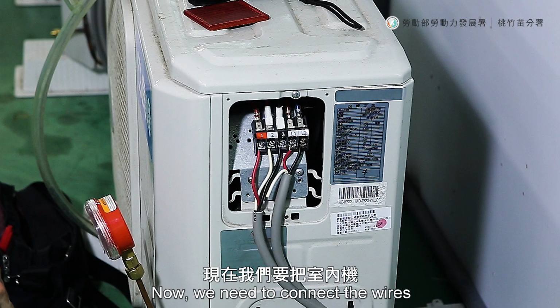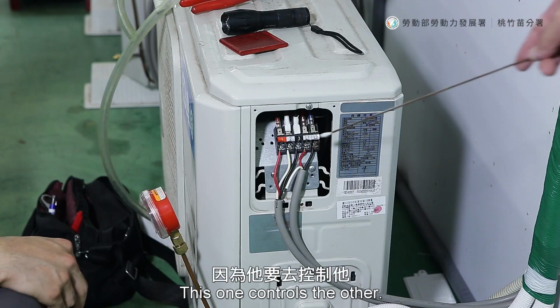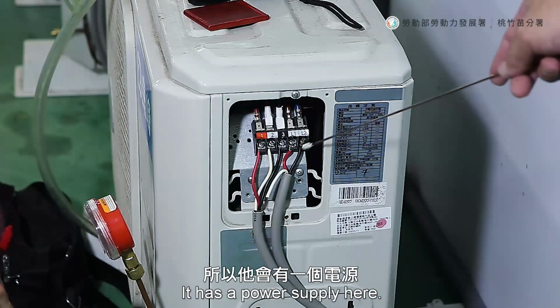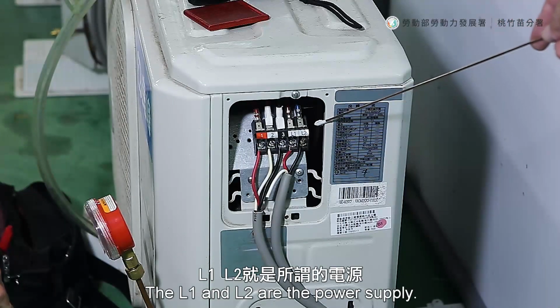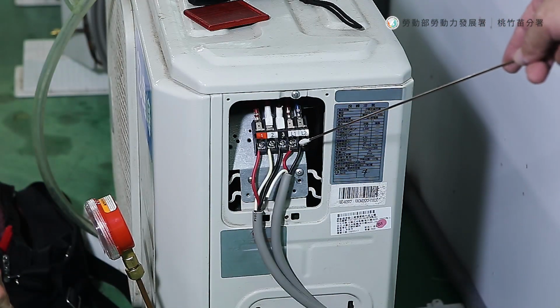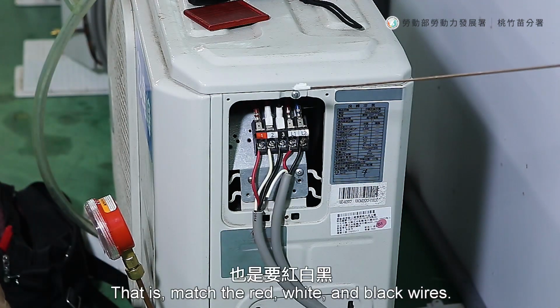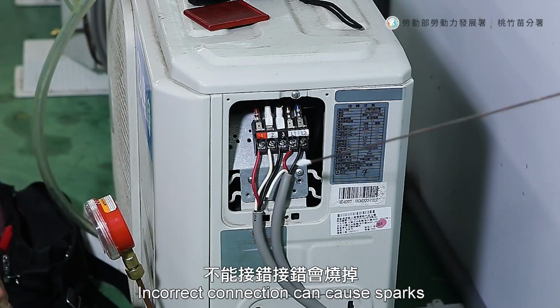Now we need to connect the wires between the indoor and outdoor units. This one controls the other, and this is the power supply from the outdoor unit. It has a power supply here, don't do it wrong. The L1 and L2 are the power supply. They're numbered 1, 2, 3, and red, white, and black wires. We need to wire our indoor unit accordingly. That is, match the red, white, and black wires. Each should match with its counterpart. Incorrect connection can cause sparks.